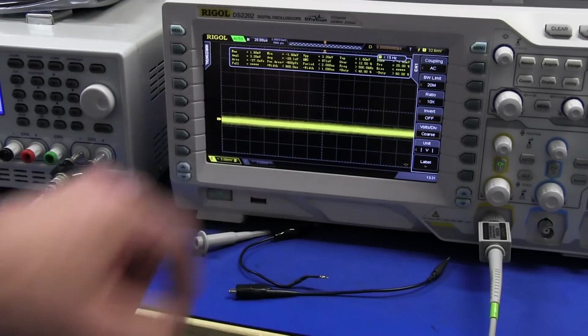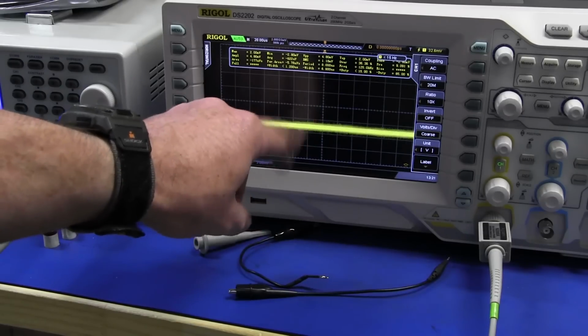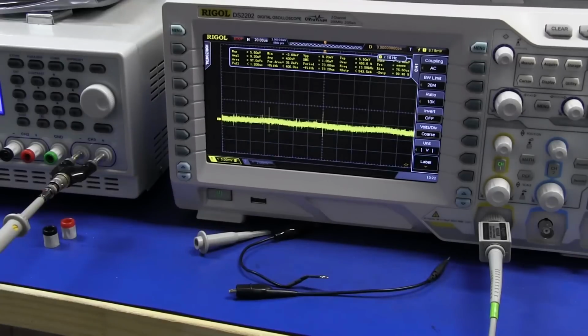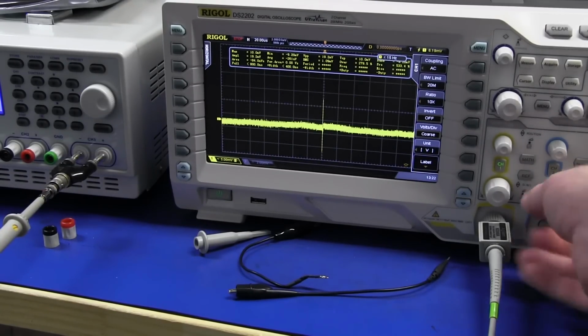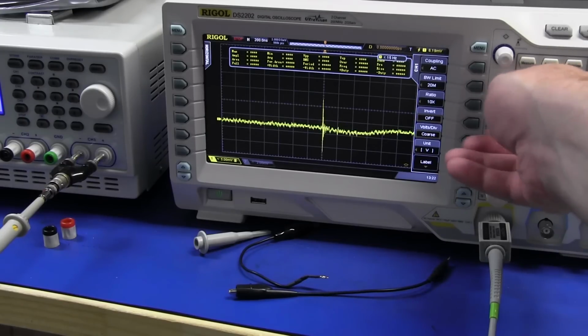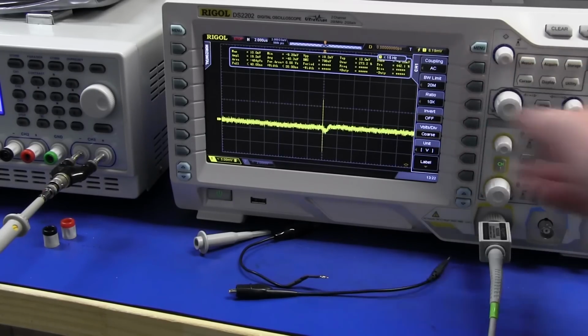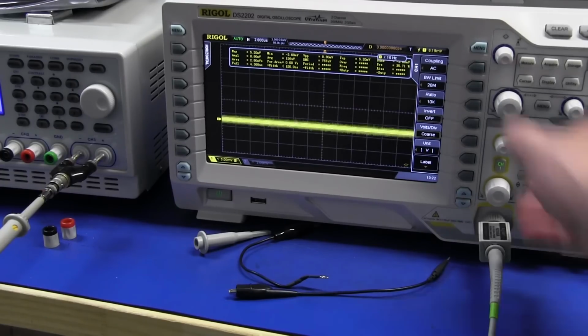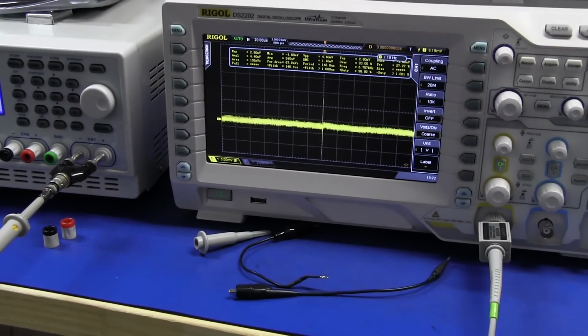That, folks, you still get the occasional high frequency glitch in there. You might be able to see. In fact, we can probably even trigger off that. And there we go. Yep, we can actually trigger off that. It's the occasional little high frequency pulse switches coming through, but not a big deal. So there you go. Now we can measure our noise with reasonable performance.